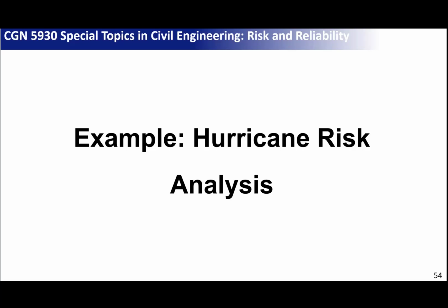So this is an example on multi-hazard hurricane risk analysis. For flood, it was simple because it's only one hazard intensity, flood depth. But if we look at hurricanes, hurricanes come with wind, with surge, with waves, with wind-borne debris, with rainfall intrusion, with water-driven debris, lots of hazards. But we can get distracted by all these hazards. We had to pick something to focus on. So we focused on the direct hazards: the surge, the waves, and the wind.